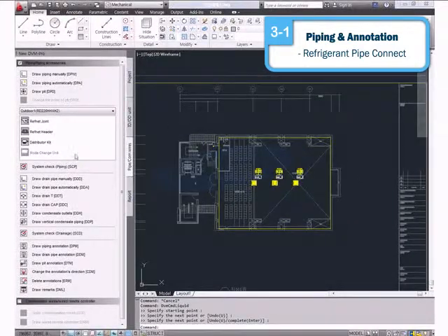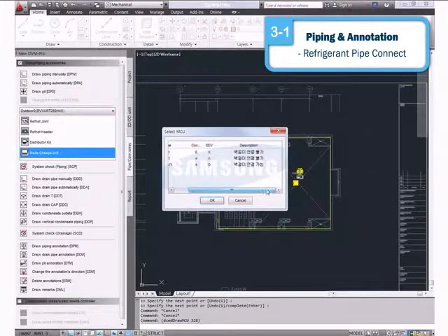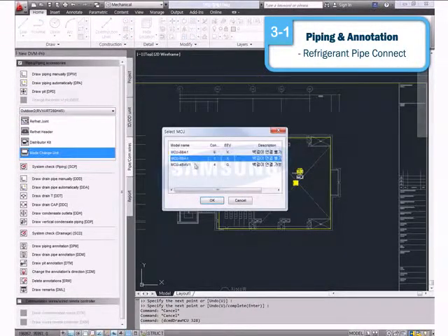Distributor kit must be connected for wall mount type indoor units. MACU must be installed for the heat recovery models of outdoor units. Be aware of the capacity limit when using the MACU.